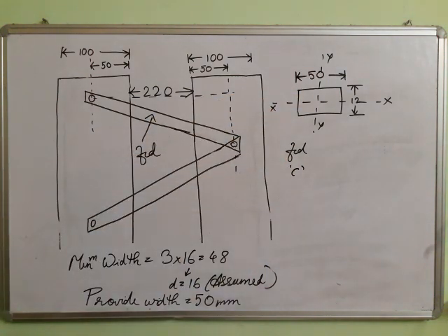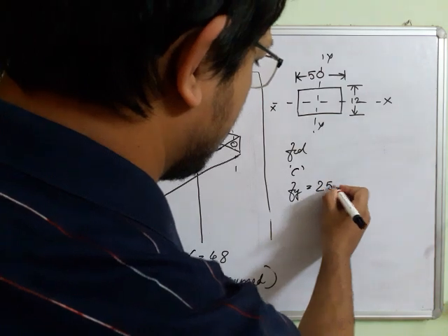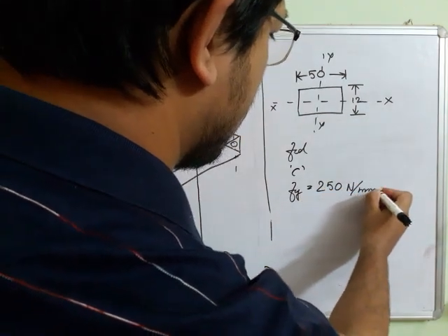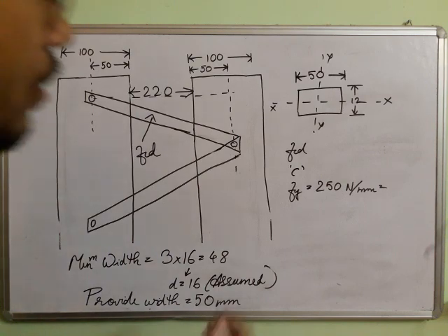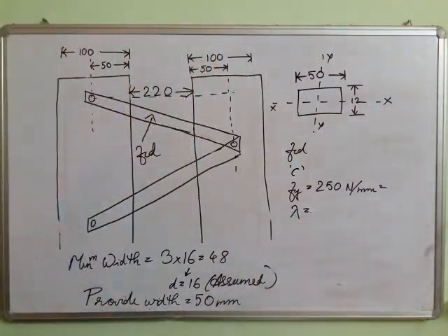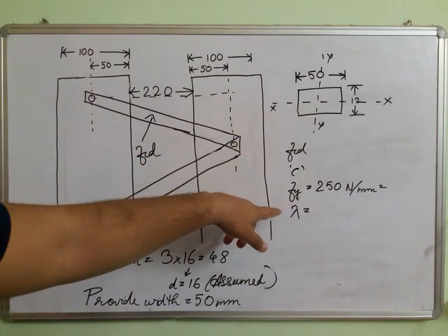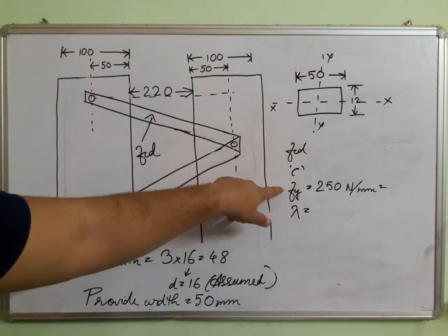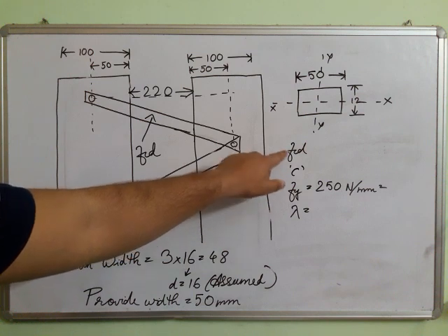Now, for FCD, first we have to know what is Fy. Okay, then if we can get the slenderness ratio, we can find out the FCD. Because slenderness ratio of the lacing, if we can get, then using the slenderness ratio and using Fy and using this buckling class C, we can use the page number 42 table to find out FCD.